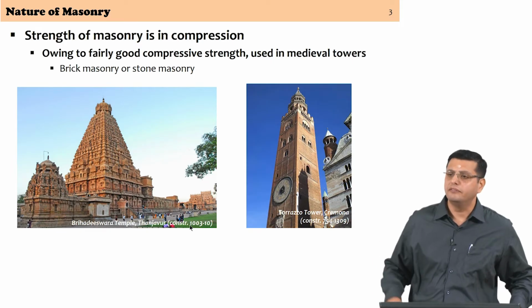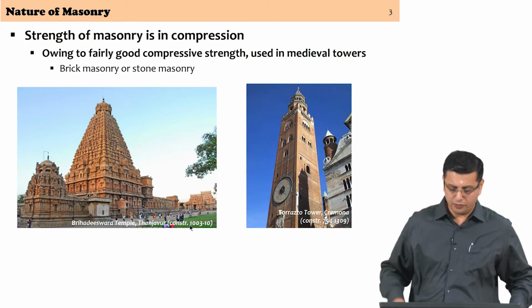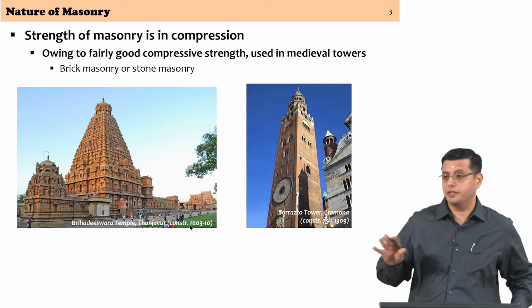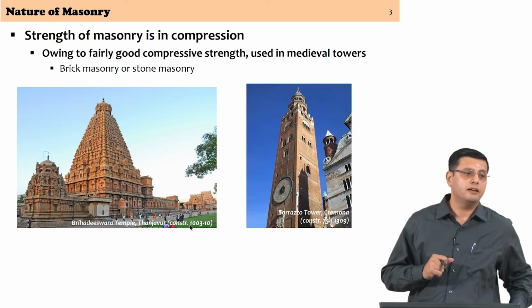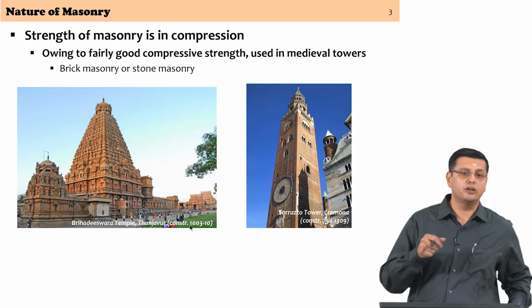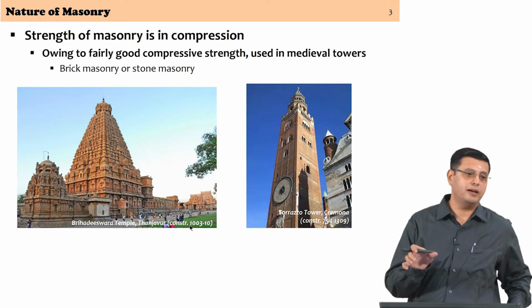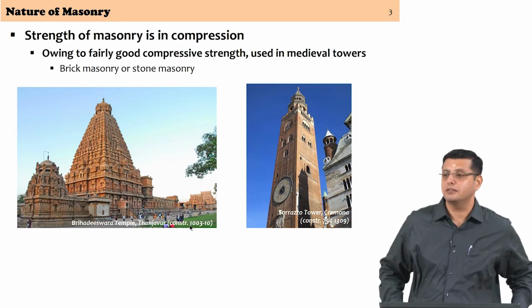Okay, that is a fairly good estimate, 1800 to 1900 kg per meter cube as the density of brick unit itself. We are not talking of density of masonry at brick unit. Only under the action of gravity forces. You know the area of cross section now, it is 19 centimeters by 9 centimeters. What is your estimate of the height to which you can construct this?